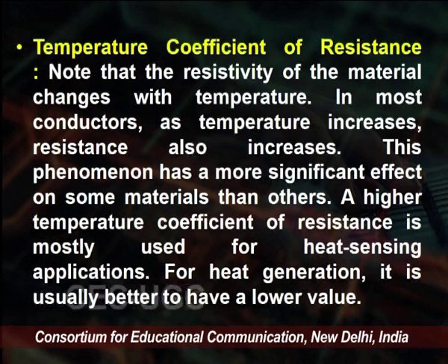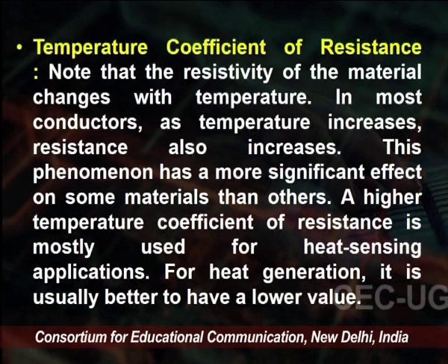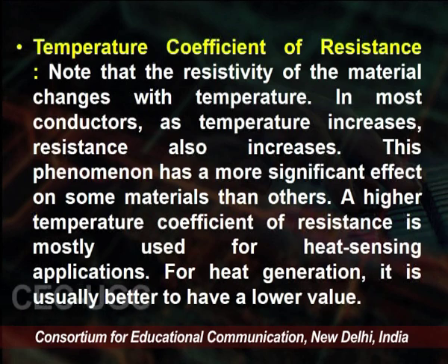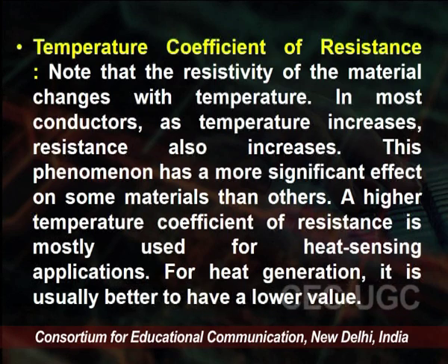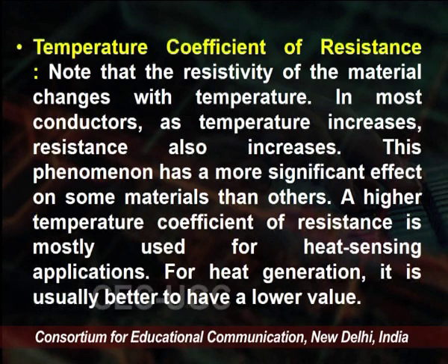A higher temperature coefficient of resistance is mostly used for heat sensing applications. For heat generation, it is usually better to have a low value. So, we should have a low temperature coefficient of resistance for high heating.